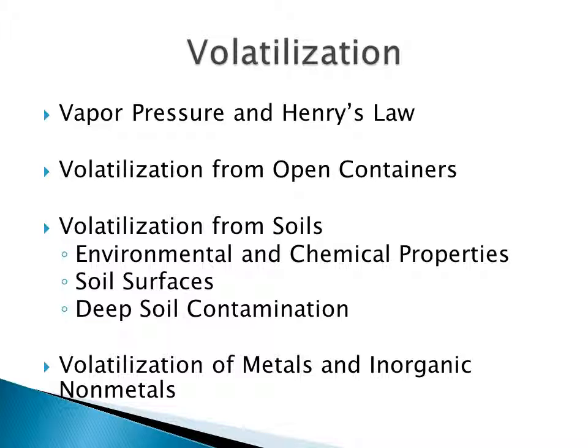Therefore, air emissions from contaminated sites and hazardous waste management facilities may become hazardous air pollutants or toxic air pollutants and result in health effects. Volatilization can also be applied as a hazardous waste treatment process to clean up contaminated groundwater through air stripping or to remediate soils by soil vapor extraction.